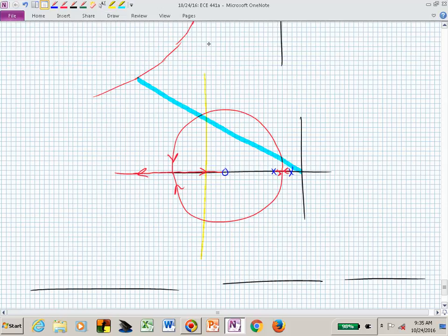I just need more colors in here. You see that? If you cranked up the gain k to get you on that portion of that root locus branch, you wouldn't be satisfying that blue highlighted percent overshoot spec. Is this making some sense? And if you had any other specification, maybe you had a given peak time spec, then you might need to have a particular imaginary piece, omega sub d.